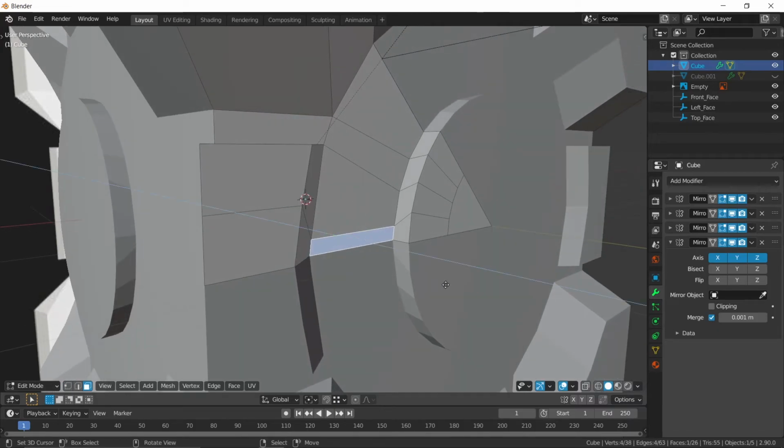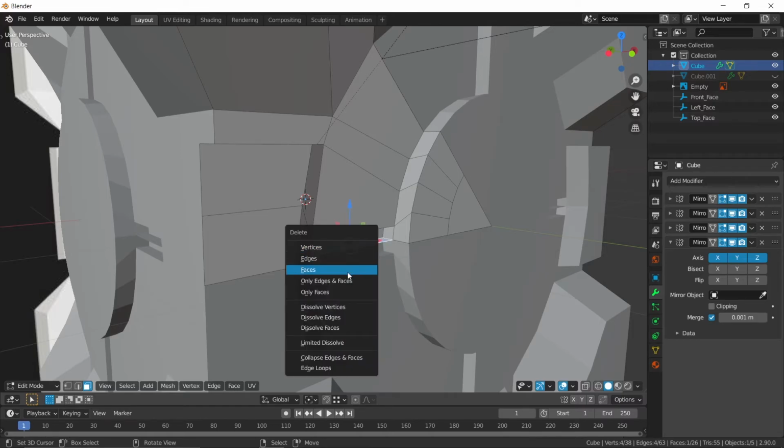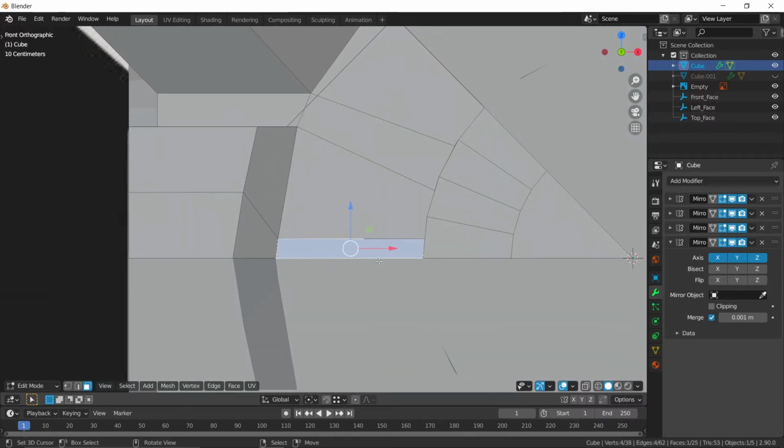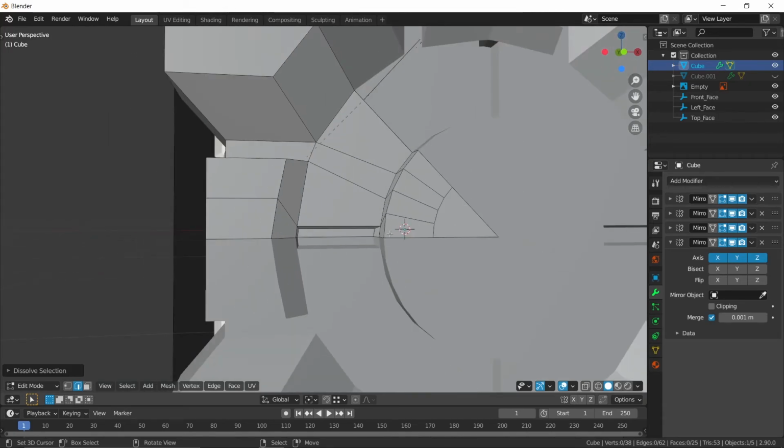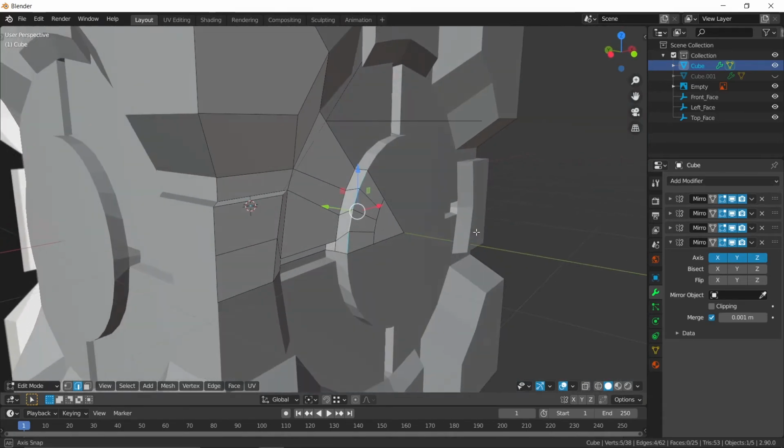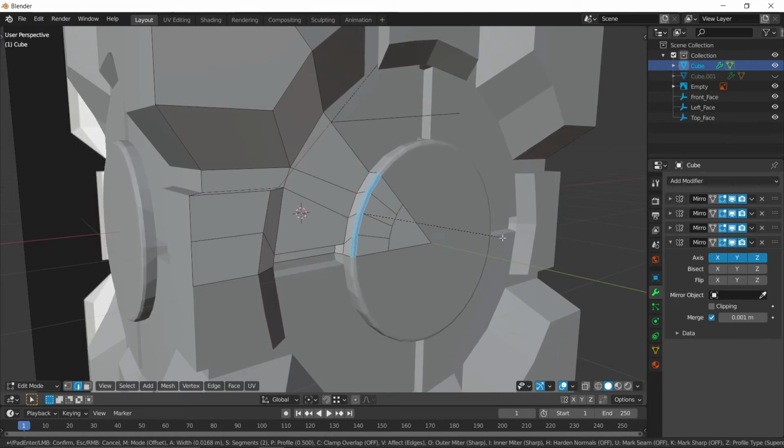Right, let's extrude this in a bit. And that seems to have created an extra face, so we'll just delete that. We'll do an inset on this face. Just press B so it goes to the boundary. And we'll dissolve that outer edge. That way we're just not getting a straight 90-degree fall off. We'll add a bevel to this here to smooth it out a little bit.